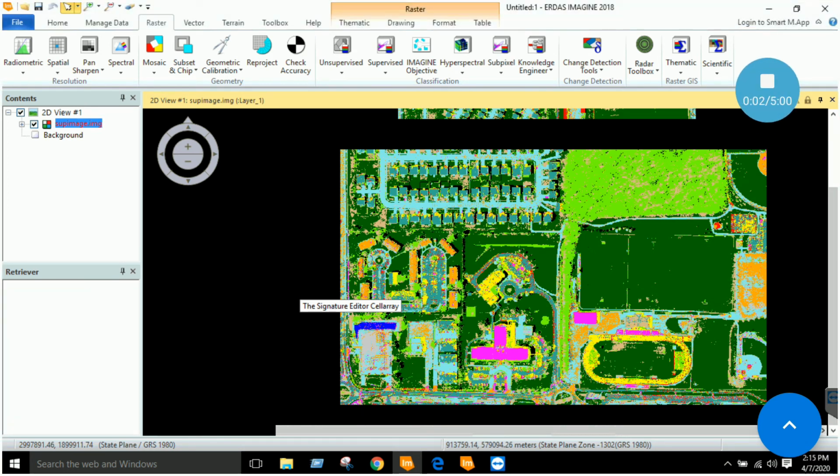Okay, we finally conclude that when we performed supervised classification on a high resolution data set, although that classification is very good, accurate, visually appealing, there are a lot of spectrally similar classes which are mixed. For example, you can see that buildings are mixed with shadows. Similarly, roads are mixed with vegetation. So we conclude that when supervised classification is performed on high resolution data, it produces non-homogeneous classes due to internal class spectral variability, because our data was high resolution data, right?